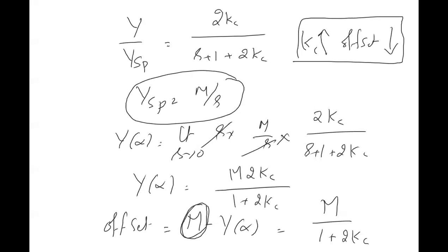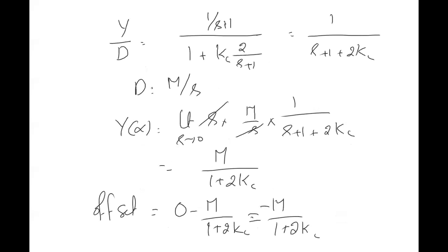How to reduce offset is to increase the Kc. So when changing the load, we can't take the offset as 0. We have to calculate. This 0 is not the offset, this is the response expected. Generally, the offset in the load and offset in the set point are the same. So like in the previous problem, in this problem, we are getting the